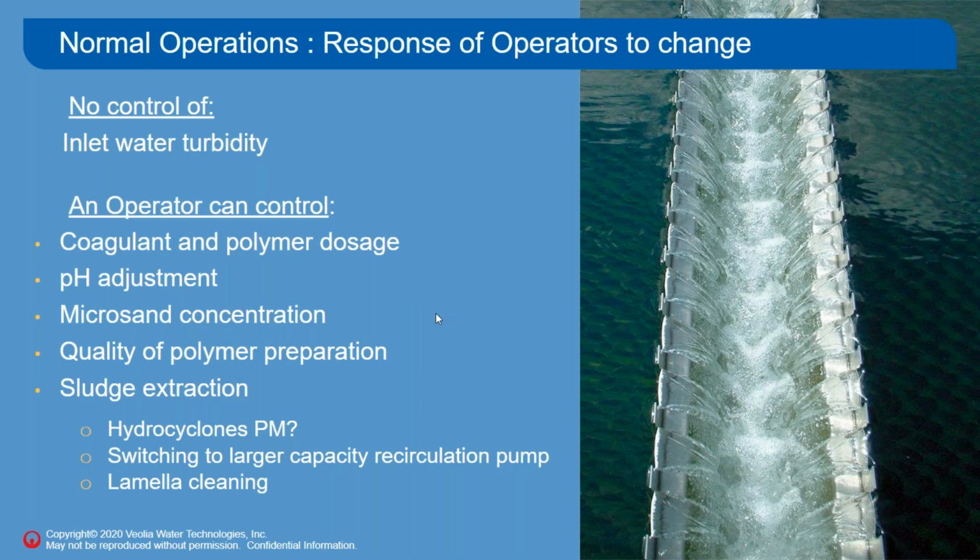But your microsand addition, or just making sure that you have a good clean microsand, because you can wear it down. You have nice fissures in there, almost like the activated carbon image that Brian had showed you. Microsand can be polished and buffed, and a lot of those fines will start to float out through your clarified effluent, and you'll be left with a sand that isn't quite as good at ballasting, or might need more polymer to grab onto that floc that you would form.